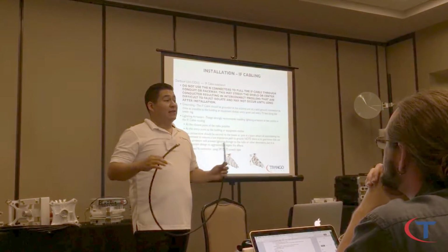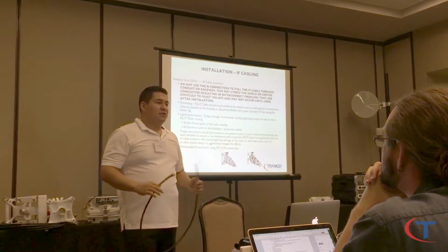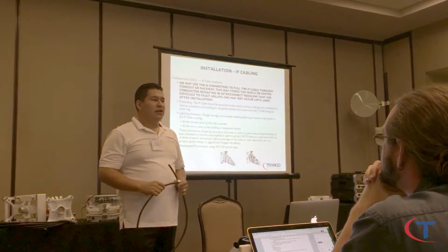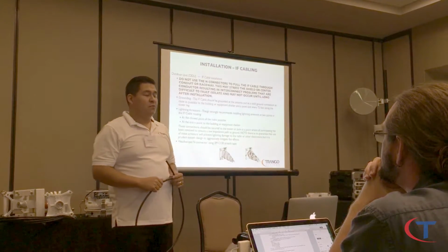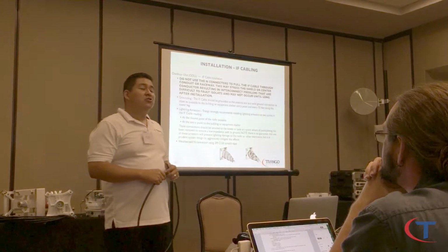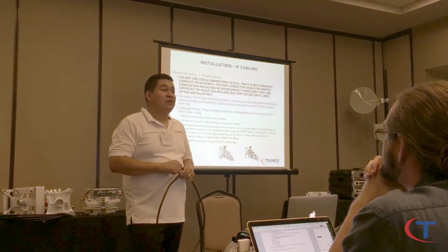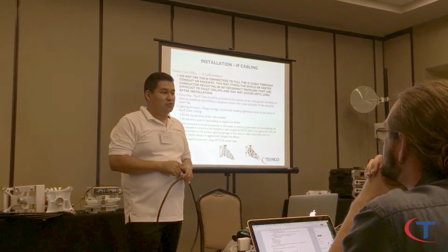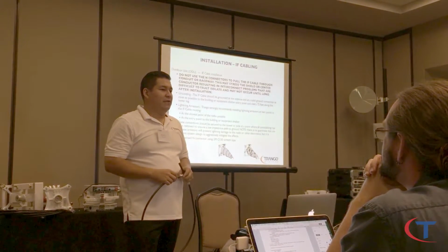You could say it's an added point of failure, but it's a good one, right? If a lightning strike comes, it's at least a line of defense. Worst case, instead of saying oh, I lost my ODU, you lost a polyphaser. Now, if you have a near lightning strike, this could also affect the polyphaser. I've seen it happen. Not a direct lightning strike, but close to the tower or next to it, it will actually mess up the polyphaser.